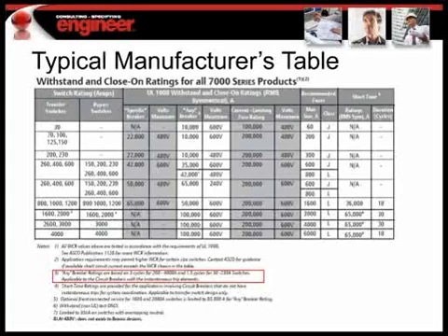The current-limiting effect of a fuse located ahead of a transfer switch works to limit the available fault current that passes through that switch, so that when you perform the UL test, you're able to basically provide up to 200,000 amps of fault current at the source, and the transfer switch will see that value significantly less than that 200,000 because of the current-limiting effect of that fuse.